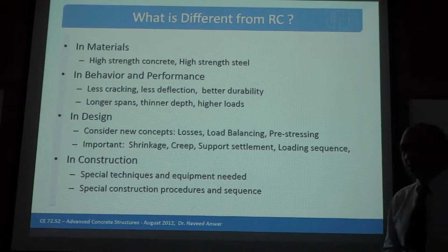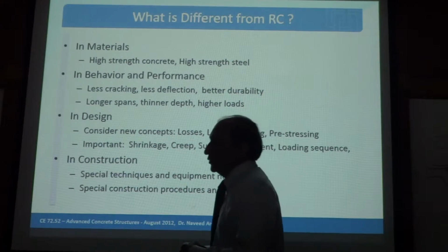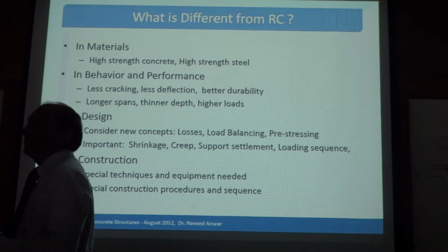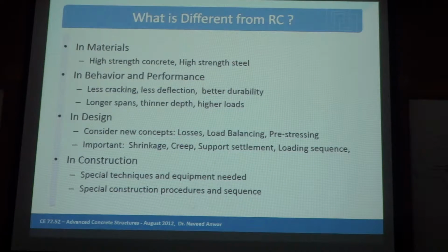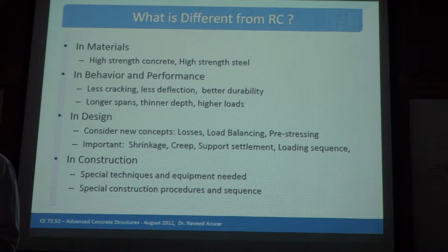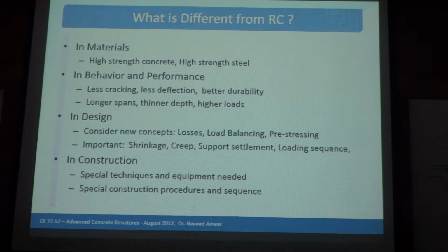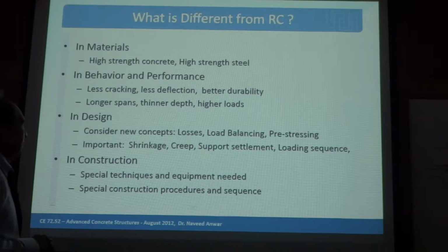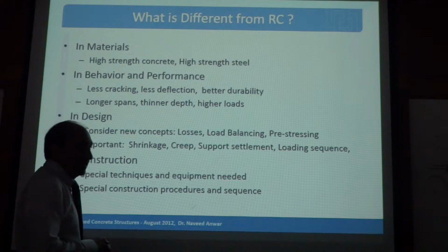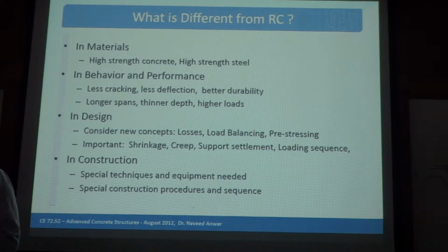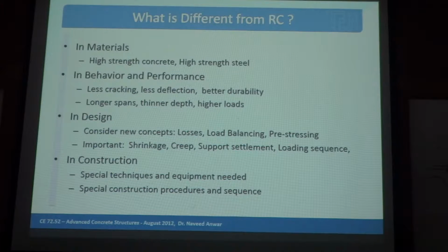Now the question is, what is different between pre-stress and reinforced concrete? Many things are different. Number one is materials are very high strength. So you cannot use pre-stressing on low strength materials. It is not worth it. The pre-stressing materials have to be really high strength, both concrete and steel. Number two, in behavior and performance: less cracking, less deflection, better durability, longer spans, thinner depth, higher loads. All of these good things come together when you pre-stress.